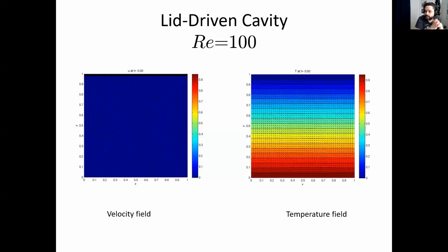So that means the only thing that we need to change is the Reynolds number. Typically, we start, here we start, with Reynolds number 100, which is perhaps also the Reynolds number that you may want to start with when developing the code, because it's somewhere intermediate between very low Reynolds numbers, where the flow is extremely boring, and very high Reynolds numbers, where the flow is quite demanding in terms of resolution.